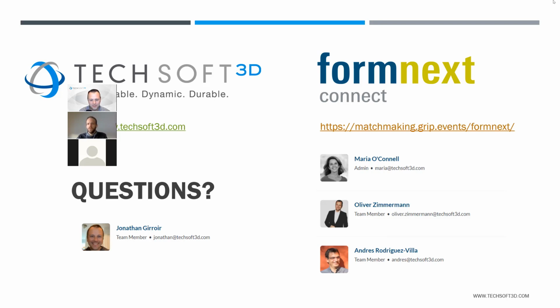So Polygonica is a library written in C, but it's available on Linux, on OS X and obviously Windows. Perhaps we're not experts in the cloud ourselves, but we have quite a number of customers who are deploying Polygonica in the cloud. The majority of them are cloud-based auto quoting type applications, similar to what Jonathan showed, where you can upload a model and Polygonica will fix it for you, analyze wall thickness, all that kind of stuff, and give the application some physical properties of the model. Then you can make various calculations about the quoting, and it does all of that automatically. There's no need for any user intervention. So that's a fairly common application of Polygonica in the cloud.